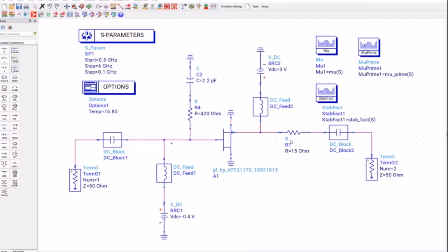Now, you typically don't like to put a resistor at the input, in series in the RF signal path, because this directly means loss. Any loss means noise figure. So if you want to achieve a good noise figure, you should not have any series resistance in the LNA input series path.